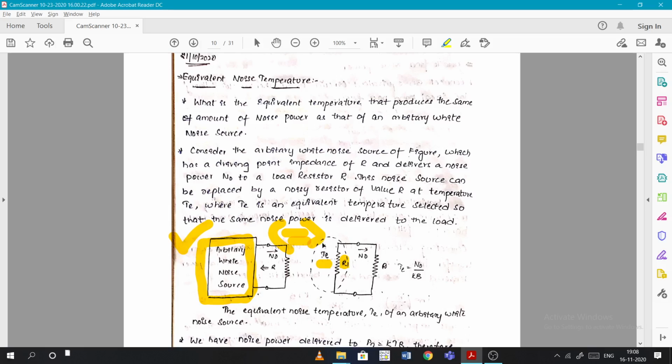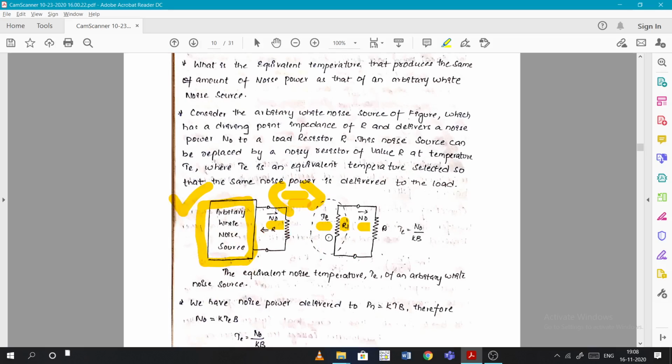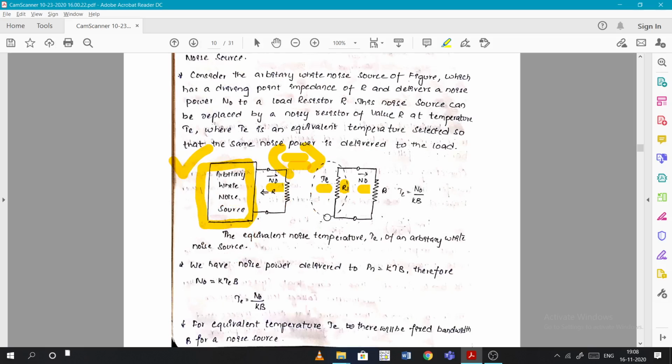While increasing T, at a particular value of T the two noise outputs get matched. So that temperature is called the effective noise temperature. Basically, you can also take it as an input one, or the effective noise temperature is for the device itself. Device in the sense an amplifier or a band pass filter, for that particular device, where there is a noise power.